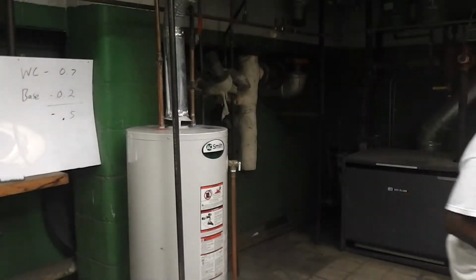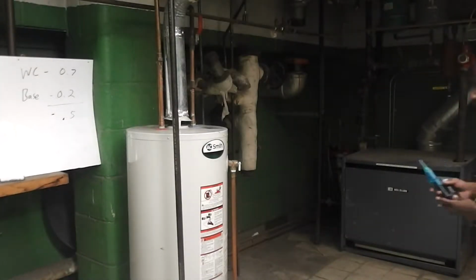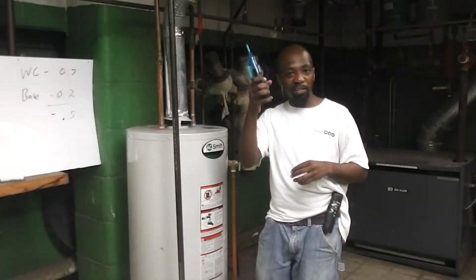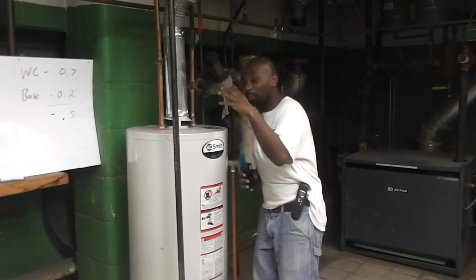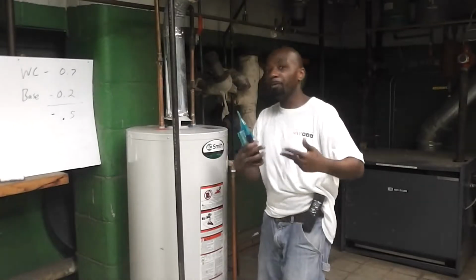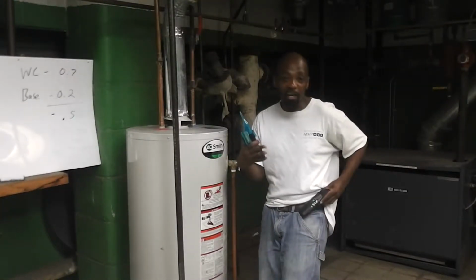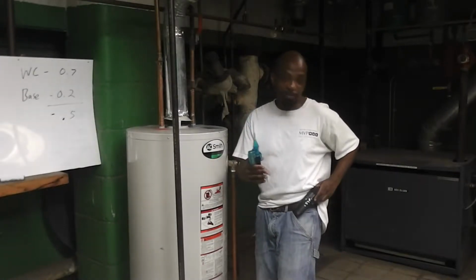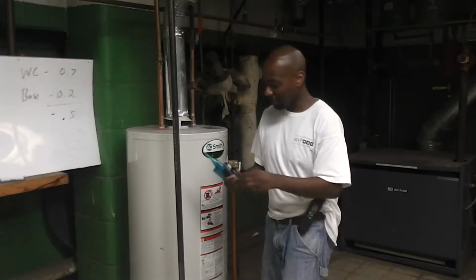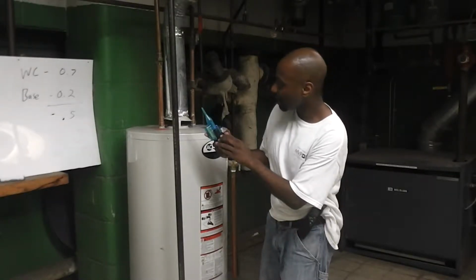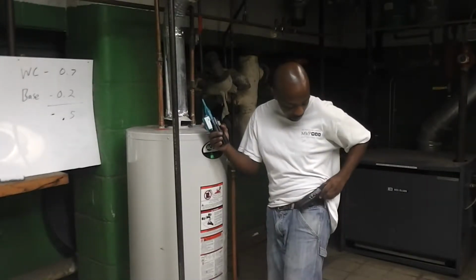Now, as that's happening, you can use a mirror. In this case, I'm going to use my smoke stick. Keep in mind, as the combustion appliance is running, I'm going to start periodically checking my ambient CO detectors to make sure it's not either 9 or 35. If it's 35, then of course I have to vacate and take the homeowners with me. So far, looking pretty good on ambient CO.